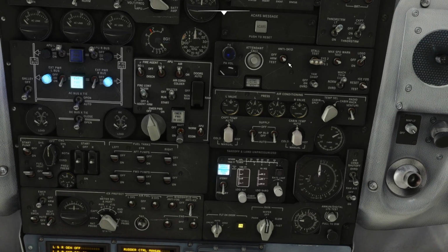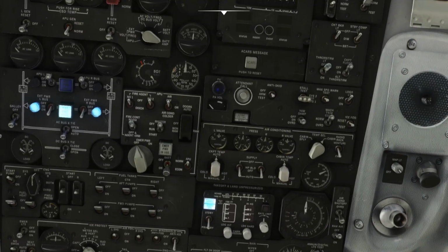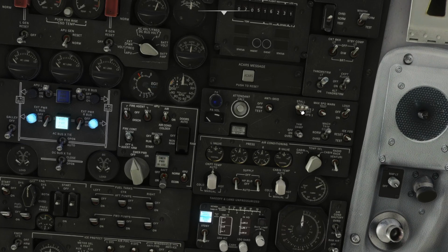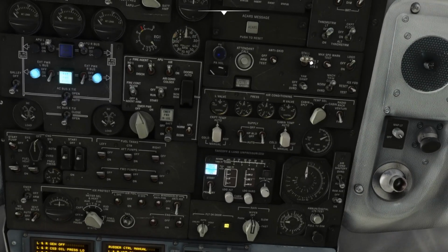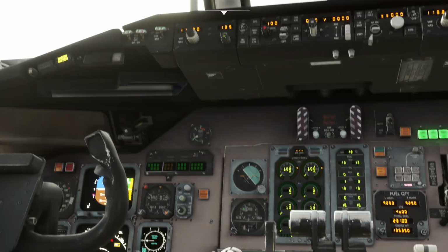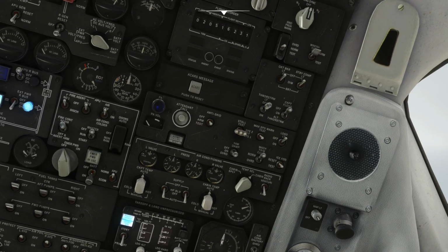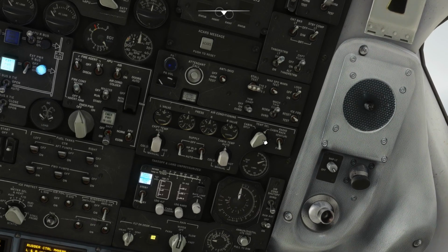So that's good. We can test the anti-skid, which should, yeah, give us 2 warnings there. Stall test. We're looking for the oral warning. And the light there. And do the max speed warning test. I believe that one's just oral. Okay, yaw damper is on. That's good. This can stay all as it is from when you start it up.